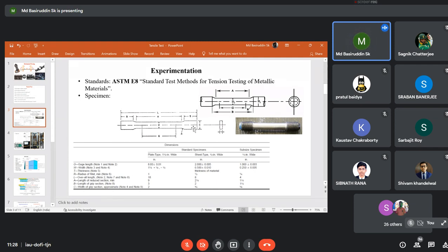Okay, not this grip portion, because if the material is homogeneous, it will be very difficult to break the specimen. Also, if the material is quite homogeneous, during gripping, at the interface of the grip or at the junction point of grip and ungripped portions, you may find that a certain notch has been created. Okay, and as you have said, if the specimen surface contains a visible notch, from there also the material will fail.